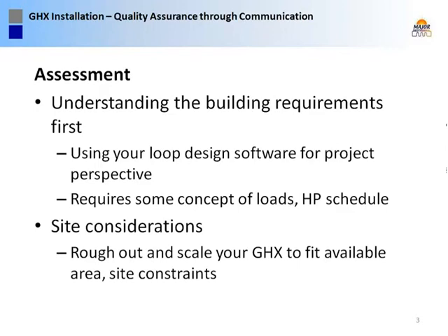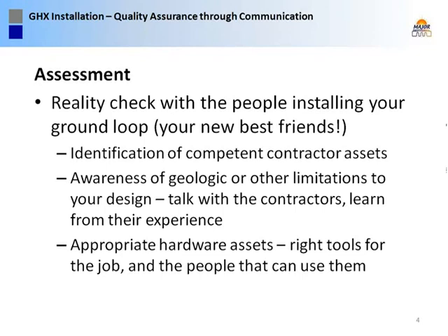And we're going to take this into the communication part now, where we find that a lot of folks can get a lot of benefit at this early stage by talking with experienced loop installation contractors. For one thing, it's nice to know if you have a depth that is very problematic, or, for example, you may want to go deeper because you have a lot of loose overburden that requires casing or whatnot. So if you're going to have to case the upper parts of the holes, it might make sense to have fewer holes and go deeper. So there's a lot of common sense things you can put into your design process at an early stage just by talking with the people that actually drill the holes.